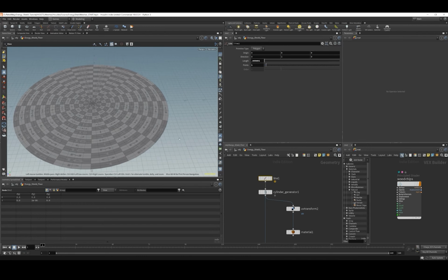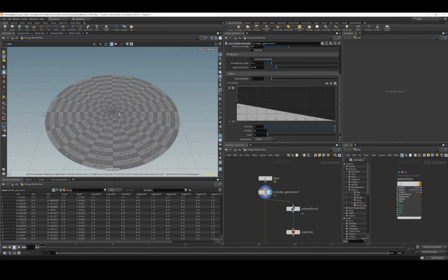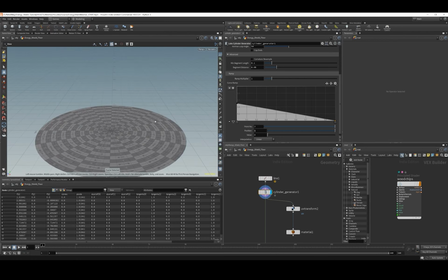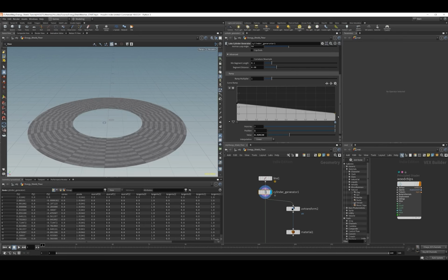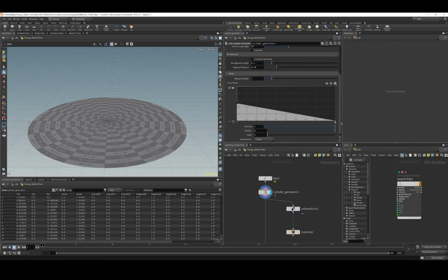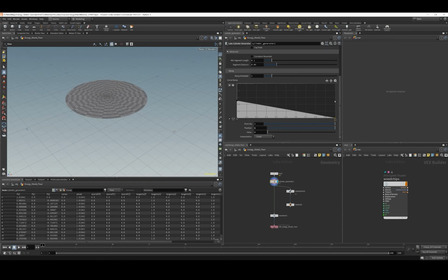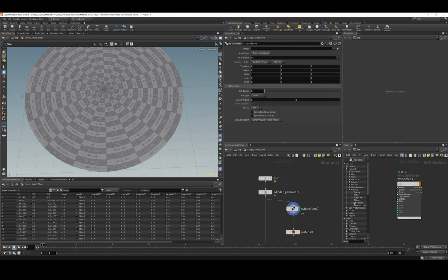And it still makes it flat. And so that's my line dropped into a cylinder generator. So that was you seeing the end result. And the way I'm getting those snapped vertices to the top, I'm just pulling them down so that they snap in like we did with our sphere. So it's going all the way to the bottom and giving us this disk mesh. And you can see that this cylinder has the same settings as the one we just did for the dome, which then if we go to our UV transform, we will see that our UVs are correct.